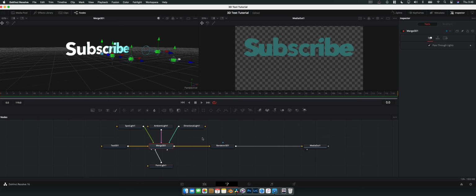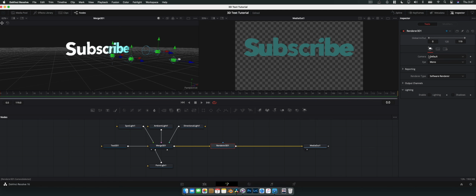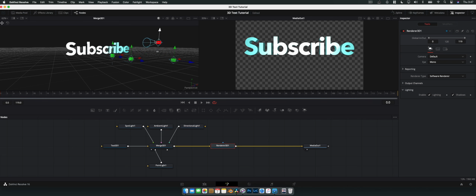Why is that? Well, now we need to talk to the renderer and make sure the renderer is going to render out lights and shadows, because by default, it does not. So let's select that. And again, in the inspector, literally it's the first thing here. Enable lighting and enable shadows. Now we're getting an exact replication, albeit in a 2D form, of what we have here in our 3D space. And if I move the lights around, we get a representation. Now everything in our 3D space is being converted into a 2D image via the renderer that can be viewed by our media out node.